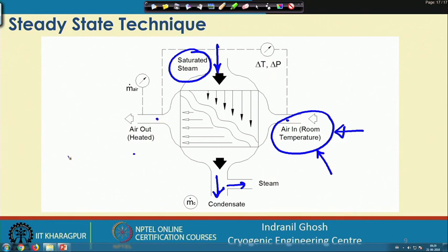And now, as we have said, this is the heat exchanger, which is the test section. What I mean is, where do we put the test surfaces? The test surfaces are on the air side, whereas the steam side has slightly wider channels, where we have a known heat transfer coefficient, for easy drainage of the condensate, and we have a known heat transfer coefficient for that side.